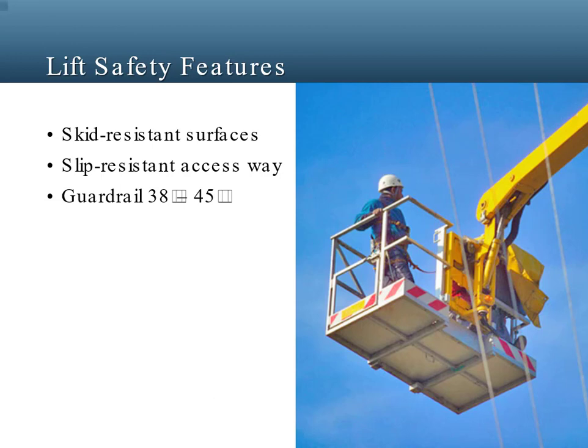The lift must be kept clear of debris, garbage, unneeded tools, grease, and any other items that could get in the way of the work, as well as create slip or trip hazards. And aerial lifts must have attachment points for the personal fall protection device for each person who occupies the work platform.